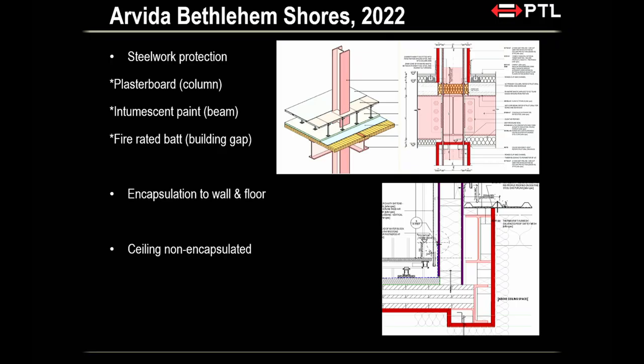So what I wanted to point out to you over here is if you focus on this picture on the top right, what it is showing you is a CLT floor with a steel column going straight through it, an I column going straight through it, and there's a steel beam coming into the steel column, being bolted onto the steel column. That's that particular detail. So again, back to the concept of system. This is a system. You can't look at things in isolation. You got to look at this particular junction here and say, what do we do about it, right?